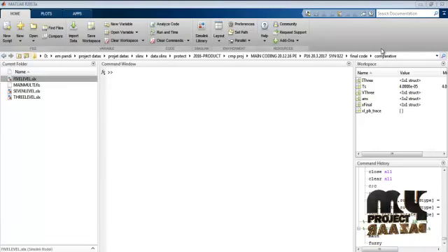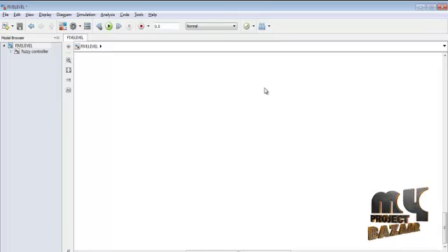Next, we see the running process of our product. This proposed implementation is done in the MATLAB simulation environment. First, open the MATLAB window and create a new model file. After creating it, we arrange the elements as per the circuit diagram, taking blocks from the Simulink library browser. In the library browser, we mainly used 2 blocks: the SimPowerSystems block and the Commonly Used block. These are used to arrange the elements as per the circuit diagram and to view the output waveforms. We connect the scopes from the Commonly Used block, and the output is shown in those scopes. Then click the run icon, and the output will be displayed in the corresponding scope.